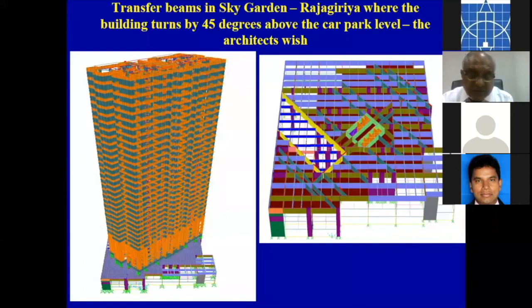So with all this, what have you done? You have increased the factor of safety in this particular member to about 3. Instead of 2, now the factor of safety is about 3. What are the chances of such a member developing cracks and undergoing corrosion? You will say the chances are much lower. Why? Stresses are much lower. If the stresses are lower, the chances for cracking will be low. So basically, you can see designing a building does not mean getting numbers from a software and then finding the reinforcement. Again, you have to look at how the building is going to behave short term and long term.